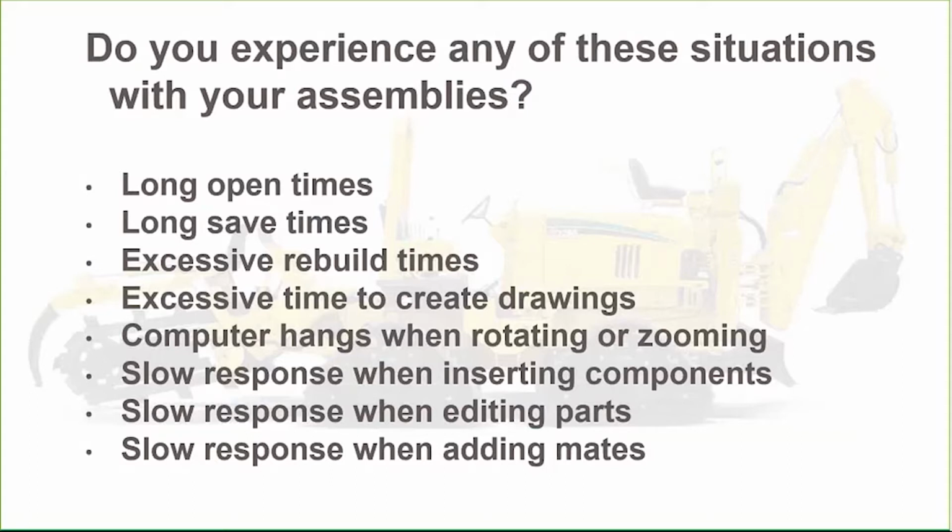So, if you're starting to experience a number of different things, how do you know if you're in that realm of a large assembly? I won't go through all of these, but if you're experiencing some of these situations, that assembly might be considered large from your perspective. A lot of people like to put a number on it. Is it 100 parts, 1,000 parts? It really doesn't matter. It is based on your experience using the tools of SOLIDWORKS, the hardware that you have in place, and whether or not you're getting acceptable feedback and response from the software. That is what dictates if you have a large assembly.